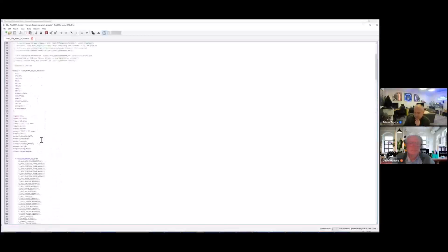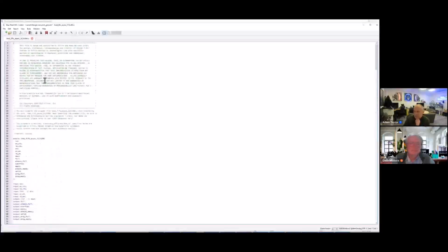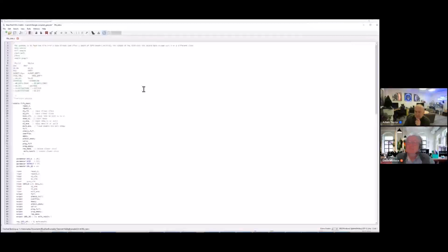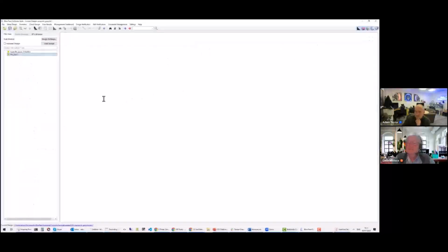Of course, because this is doing clock domain crossing, it is an asynchronous FIFO. Then on top of that, we have the actual RTL module, which instantiates that FIFO and controls the writing and the reading of data from it. And it's this that we want to check is working correctly for clock domain crossing.